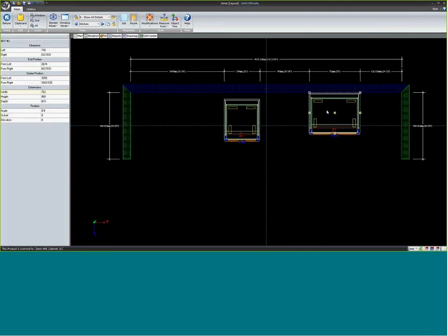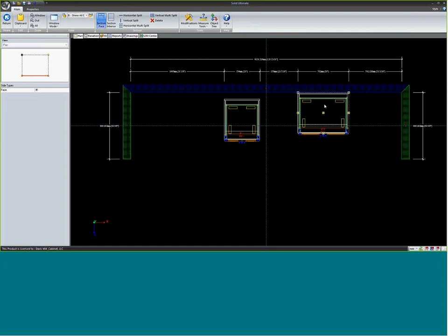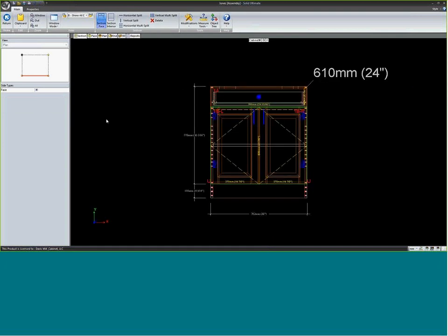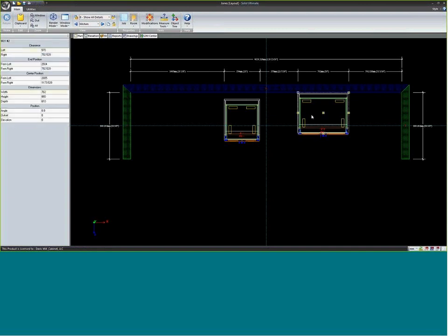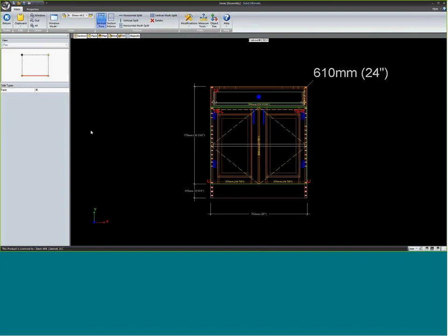Now, in this cabinet, we're going to change the next set of parameters. We want to change the dx, dy, and dz. The dx, dy, and dz refer to the size of this cabinet. So the dx of this cabinet is its width. The x dimension is the width of this cabinet, at the cabinet level, to illustrate this. By the way, if anybody's ever wondering if you're on the cabinet level or the room level, it's pretty easy. I get this question fairly commonly, but if I see walls or I see multiple cabinets, I'm room level. If I only see one cabinet, I'm on the cabinet level.